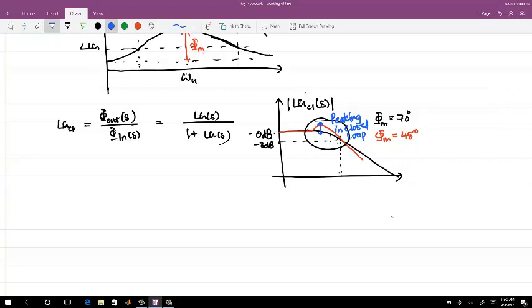What will this lead to? This will lead to a ringing in the phase output. When you give any step, any input change, there will be a ringing in the output. So that is the first artifact of a lower phase margin you will see, other than the stability. If you have a phase margin of 45 degrees or 60 degrees, and there is nothing else in the system which is going to change this phase margin, you are still stable.